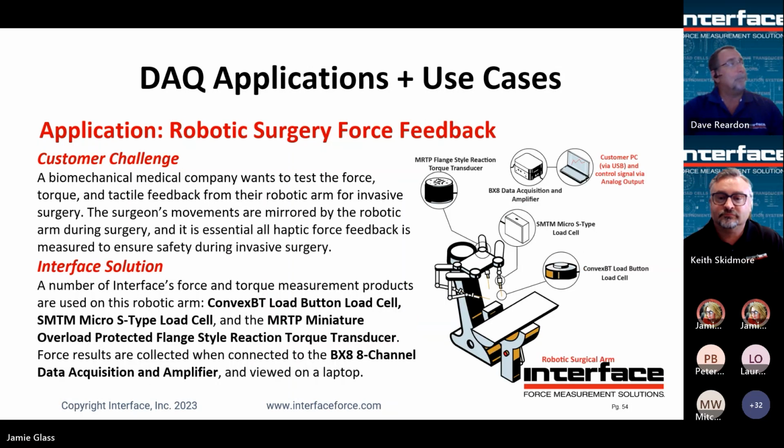Next slide. So this is a robotic surgery force feedback application. A lot of these systems have sensors embedded in them for measuring, say, torque, force, displacement. Also, when the operator uses the system, there needs to be force feedback and haptic feedback into controls. So this would be using BX8, where you have data logging to a PC, also actively outputting the sensor signals via analog outputs back into the controller for force feedback.